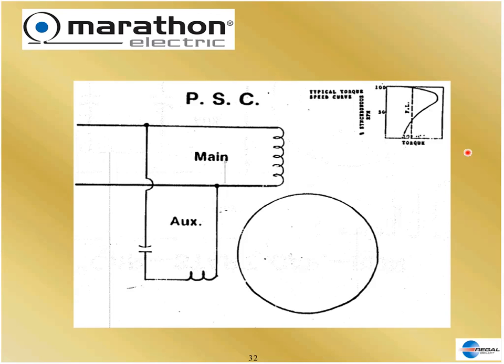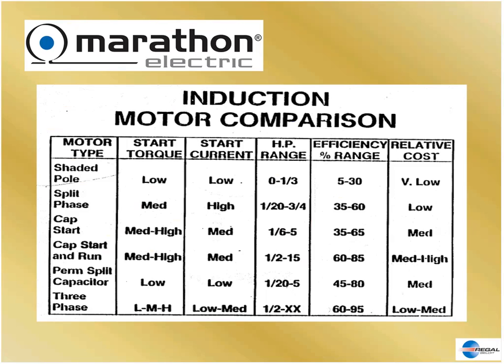Air conditioning, furnace people love this motor. That's what it was invented for, because it's reliable and it has no switch to fail. Air conditioners and furnaces switch on and off a lot of times. They cycle on and off depending on the weather. The more times you actuate this switch, the more times it clicks. It's mechanical. It will fail eventually. It only has a certain life. So it is eliminated in the PSC.